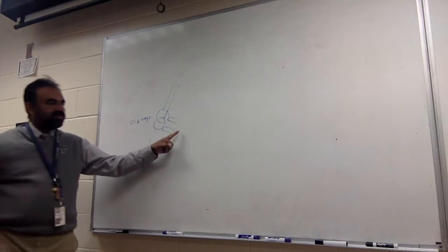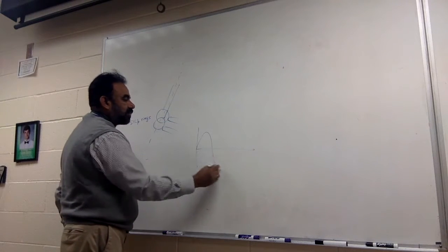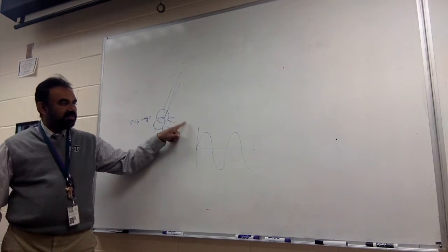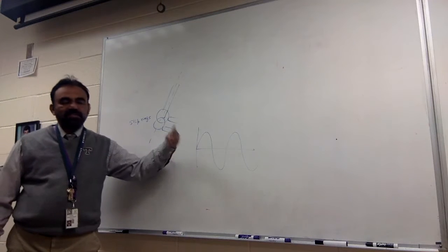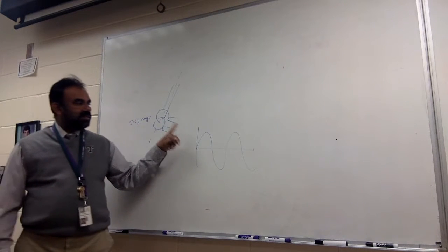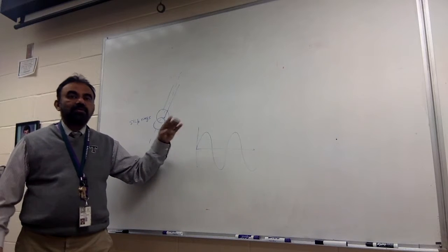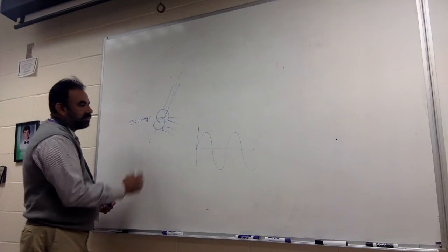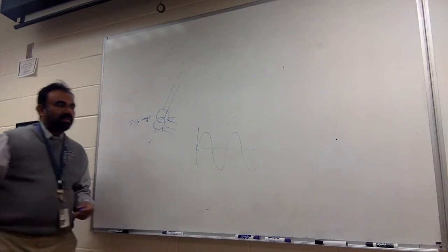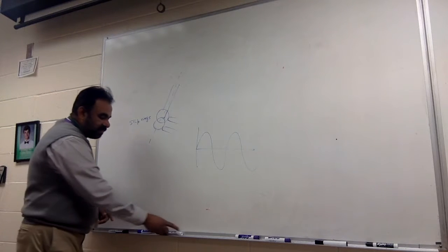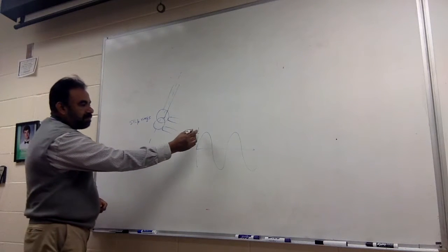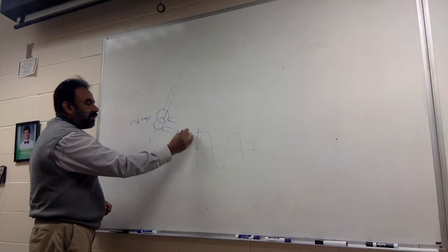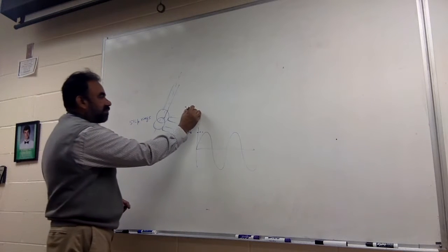And the voltages that come out from here are alternating, and you saw that. Sometimes this side is positive, and sometimes the other side is positive, and so on. So the induced EMF is alternating, so also the induced current will be alternating. How many times it alternates per second is the frequency F. We saw that the peak was omega BAN, where omega is 2 pi F.